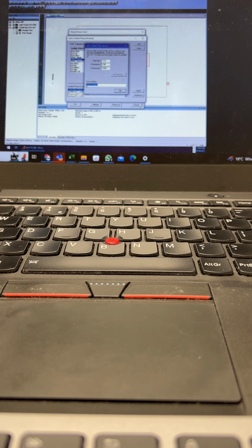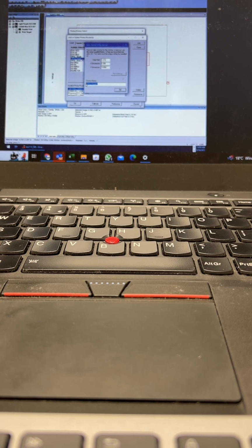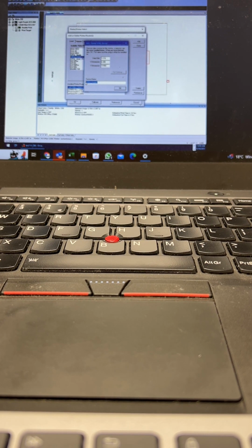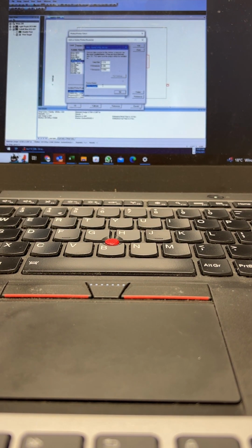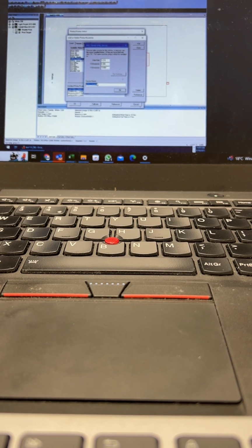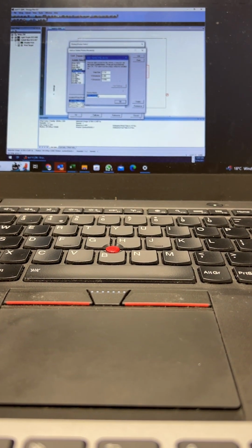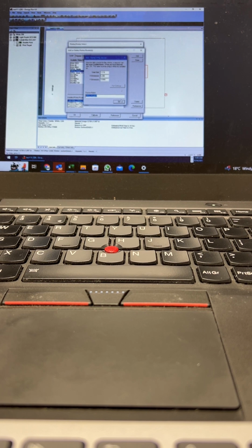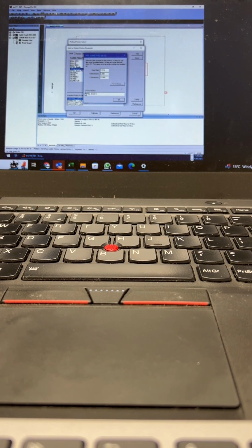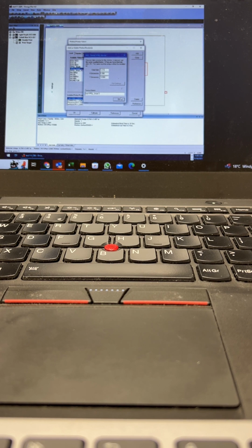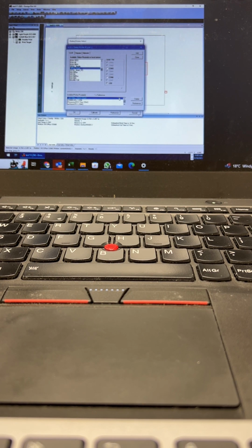So if you're installing a Joe Blow's plotter, you can name it Joe Blow's plotter. It doesn't matter what the name is. Usually I'll do a name and then put HPGL at the end of it, just so you know that it's one that you installed, not one that Gerber supplied as a default. So we'll just call this one test. So that's how you'd install a plotter.